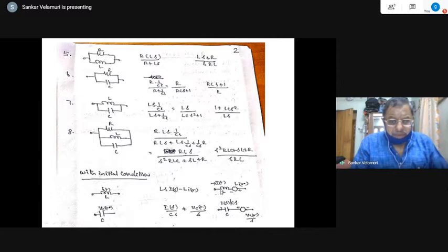Because if you consider plus and minus here, it opposes this. So because this is plus, this is minus, because in the direction of the current, if you take the corresponding flow, this becomes the voltage source. Like I0 minus is the current flowing through that, the steady state current prior to the instant of switching. You have to imagine it like that, which will be incorporated subsequently. And L into I0 minus becomes the voltage source.